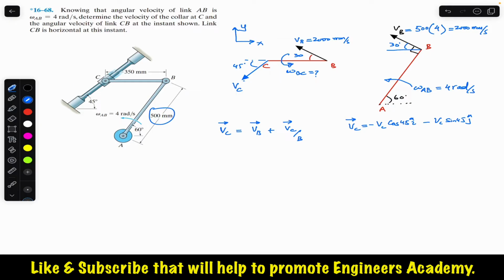Similarly, we can write VB as a Cartesian vector. Now as we can see, VB is making 30° with the horizontal, so the cos component will be in the negative x and the sine component will be in the positive y. VB magnitude is 2000. So we can write 2000 cos of 30 in the negative i and 2000 sine of 30 in the positive j. So this is the Cartesian vector representation of VB.